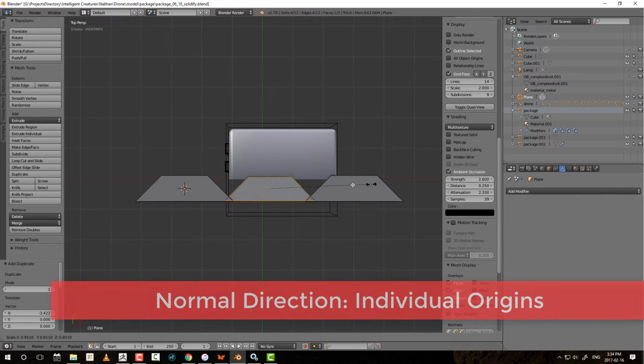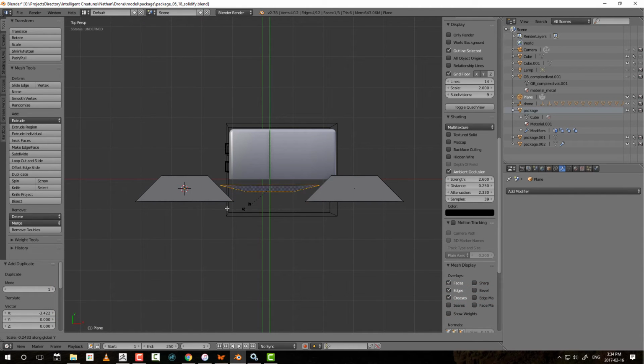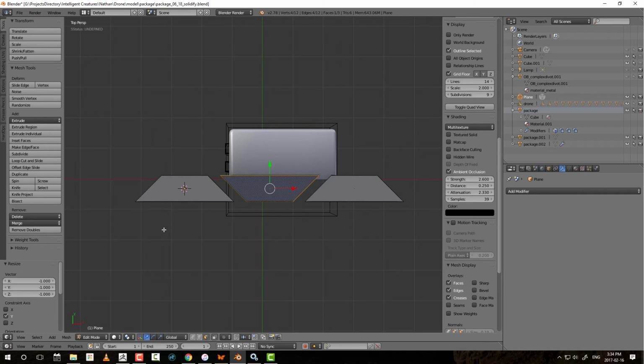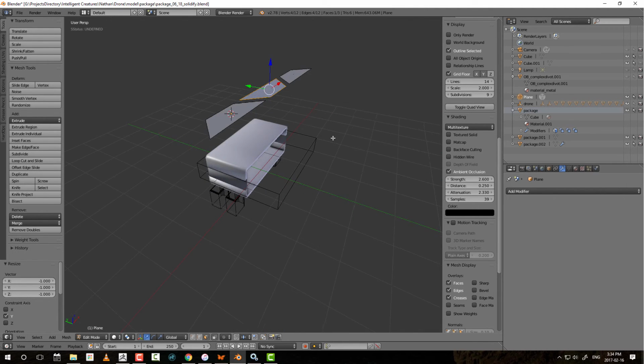Now I'm going to scale, but I'm going to scale and constrain on Y, and then I want to press Control to snap, right? And I want to make sure my negative value is, I'm scaling basically by -1, and if you go to the bottom left of the screen, you'll notice that it says scale -1 along Y, or along global Y. And then press and let go.